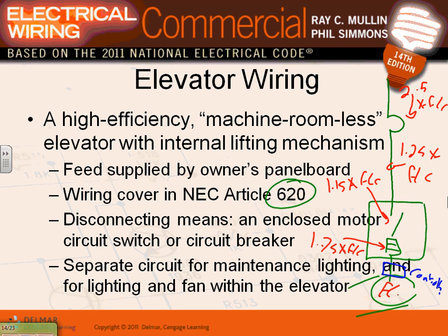Is the conductor sized for continuous duty for this? Yes, all of them, absolutely. A pump motor. Yeah, it's a pump. They treat it exactly like a pump. Actually, if you go to Article 620, they tell you to multiply by 1.25. The article that talks about it is right here, my friends.